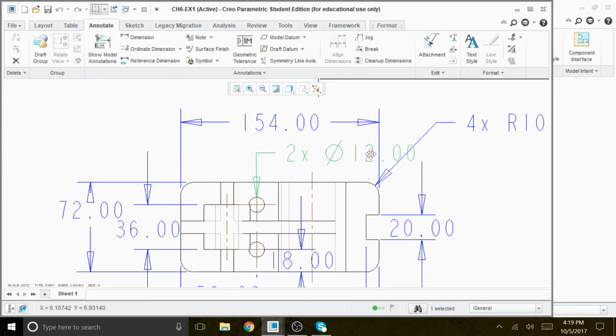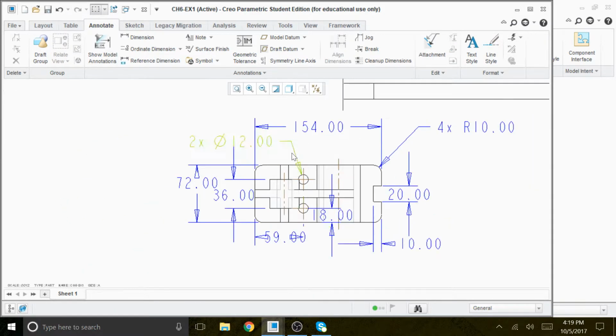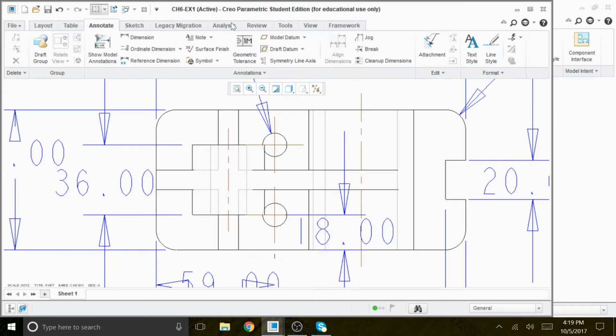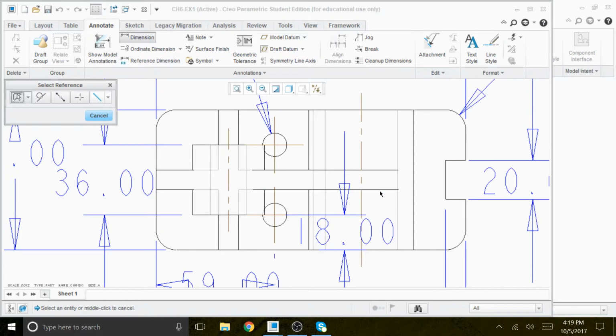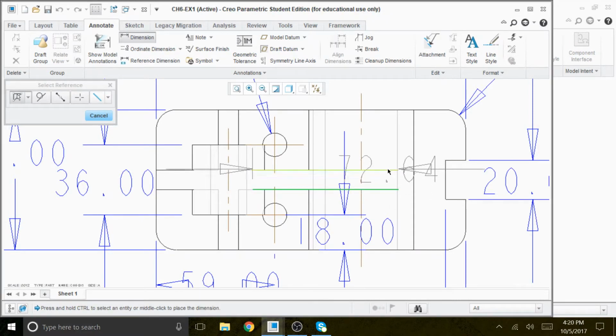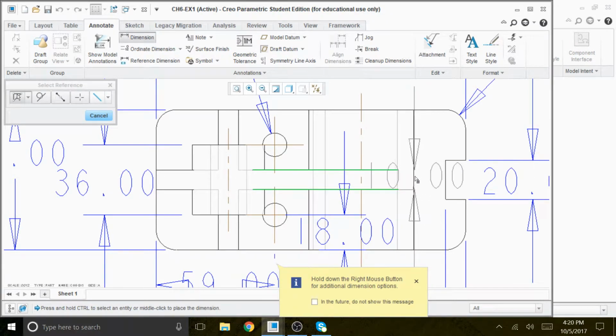Maybe we need to, okay, so that's where this, maybe we can go to this side. Okay, all right, and that's all, and I think we're done with the dimensioning here. I think I gave all the dimensions, and then this is the diameter of, oh, okay, the thickness of the rib. We need to give the thickness of the rib, it should be 10.